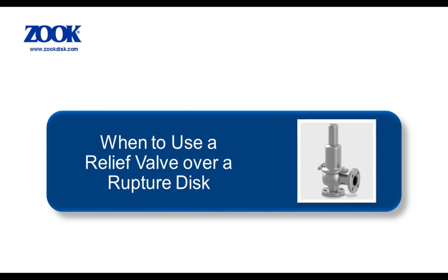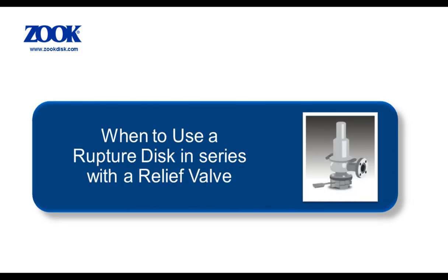There are many cases where a relief valve is actually the preferred method of pressure relief. The most common would be in processing or continuous service applications, where downtime is a problem. A valve will typically reclose after relief, whereas a rupture disk would need to be replaced prior to restart-up.